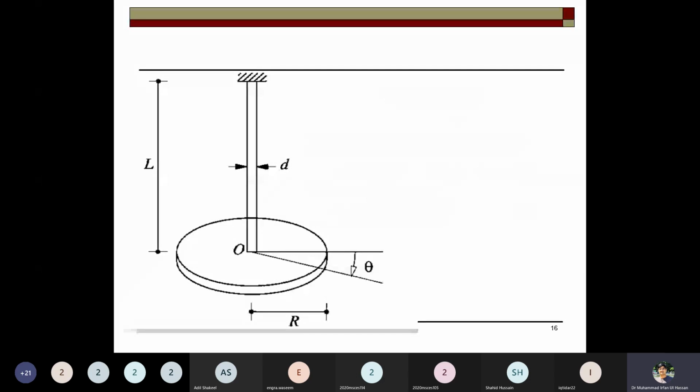The case that we discussed previously was about writing down the equation of motion for a linear system when linear translation is produced. But when there is a rotation, where displacement is in terms of rotations, not linear movement, how do we write down the equation, and what changes occur? When the beam is a cantilever beam, you say the displacement is linear, stiffness is 3EI over L cubed, and you can write down the equation.